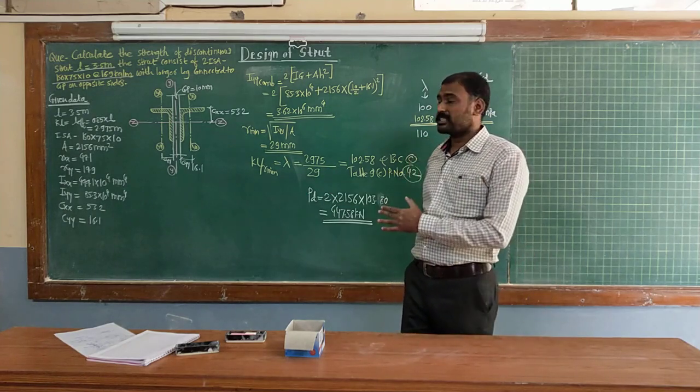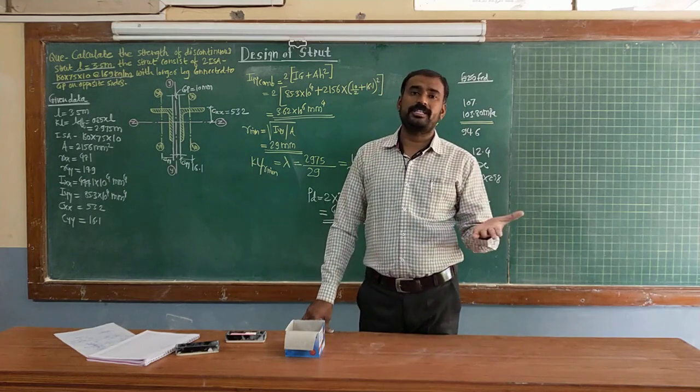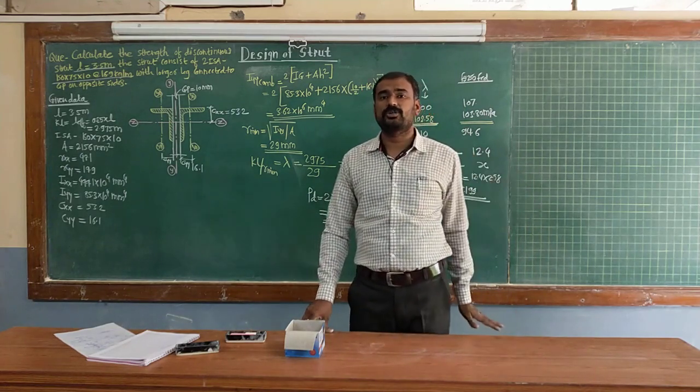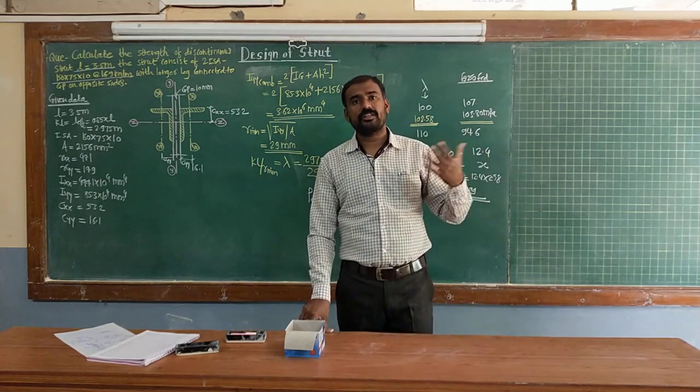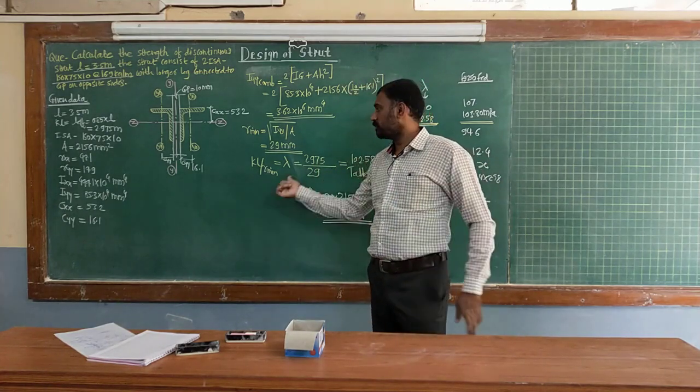Usually in some cases these sections may fail in design problems, so try to adapt the value of 0.7, so you will get a greater slenderness ratio, and for greater slenderness ratio your value is going to satisfy the given loading condition. So here the numerical is completed.